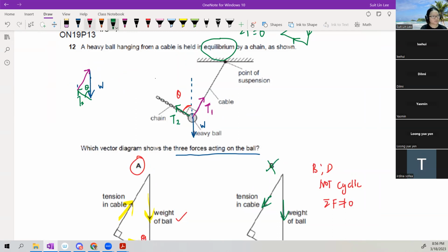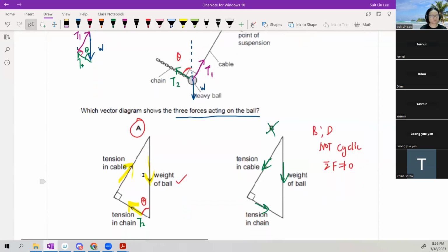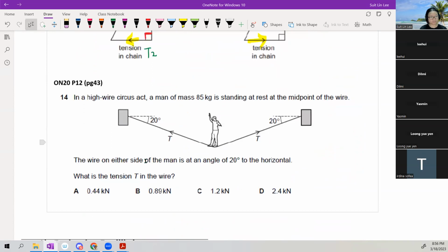And you're thinking, where's the 90 degrees? Well, my friend, the 90 degrees is here. 90 degrees between T1 and T2. Okay, which basically is this diagram. So diagrams are straightforward. Calculation is also straightforward if you already have values. And since the angle is the same, because the tension is the same, I'm just going to use equilateral triangles. But I would take a point on the rope here on his feet as my equilibrium position. So at this point, he's 85 times g, 9.81.